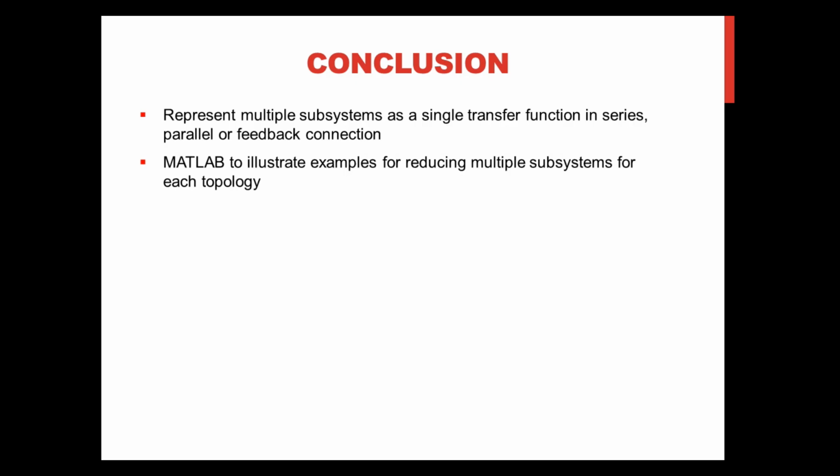In conclusion, we discussed how to represent multiple subsystems as a single transfer function in cascade, parallel, or feedback form. We also used MATLAB to illustrate examples for reducing multiple subsystems for each topology.